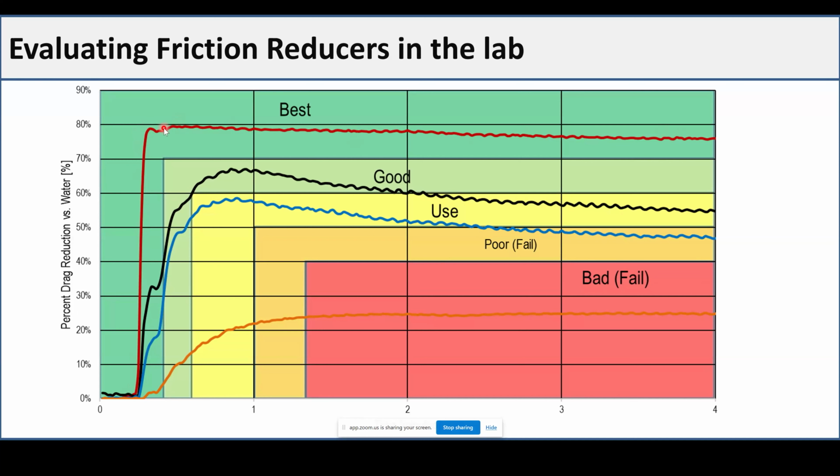Because what's happening as you are injecting, the polymer tends to be decomposed a little bit, broken by the shear. And that will affect the friction reduction with time. So as time goes up, as you are pumping, cycling the polymer over all that time, it starts to degrade and starts to have a lower value than the maximum value. So with this value, you would like the polymer degradation to be as minimal as possible. So we have it there. We call it the best one.